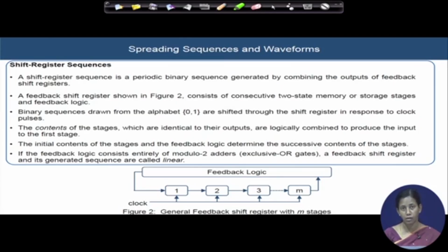It has a nice autocorrelation function, but the problem is that in any practical system design, for synchronization purposes, we understood that for direct sequence spread spectrum as well as for frequency hopping spread spectrum, timing, phase and frequency synchronization will be very critical, because you have hopping involved in frequency hopping spread spectrum, and in direct sequence cases you have to be well aligned in time with the incoming signal, otherwise it will be very hard to despread your signal and demodulate your signal.